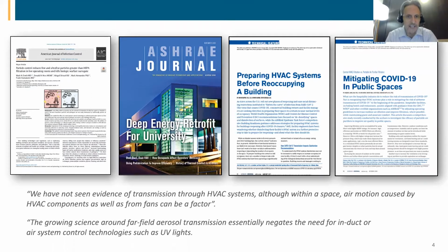ASHRAE, the American Society for Heating, Refrigeration, and Air Conditioning Engineers, has come out with several peer-reviewed ASHRAE journal articles that have talked specifically about SARS-CoV-2 in the indoor built environment. And they have said with regards to SARS-CoV-2 that we have not seen evidence of its transmission through HVAC systems, although within a space, air motion caused by HVAC components, as well as from fans, can be a factor.